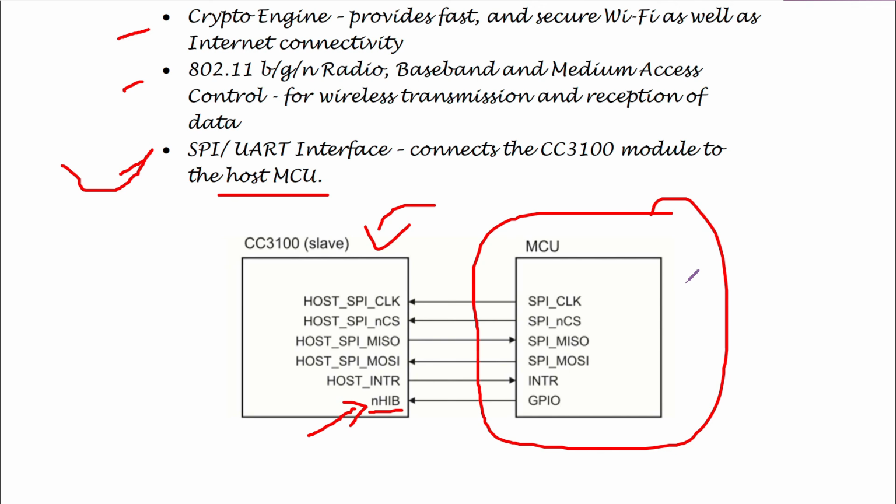So this is how you connect any microcontroller to some add-on module or peripheral that grants it Wi-Fi capabilities or Bluetooth capabilities. It can be anything. So you only have to take care about the kind of interfacing you are going to be doing. That is whether it is UART based, SPI based or I2C based. There are several products, several devices available in the market that have different interfacing options available so that your existing microcontroller can become IoT compatible.